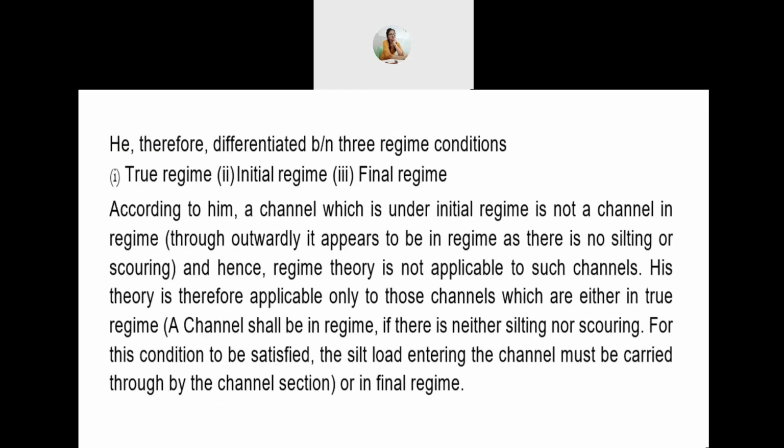So he therefore differentiated between three regime conditions: true regime, initial regime, and final regime. According to him, a channel which is under initial regime is not a channel in regime. True, outwardly it appears to be in regime as there is no silting or scouring, and hence regime theory is not applicable to such channels.